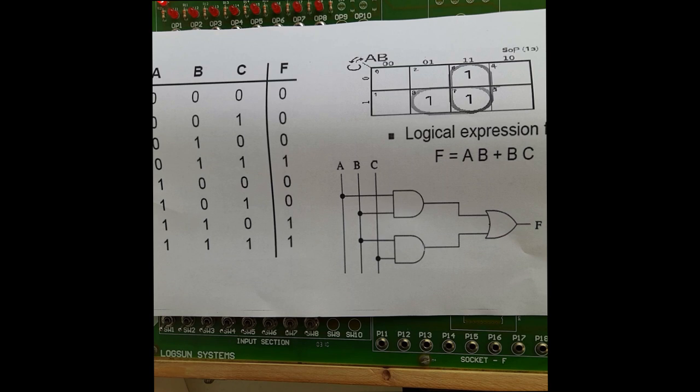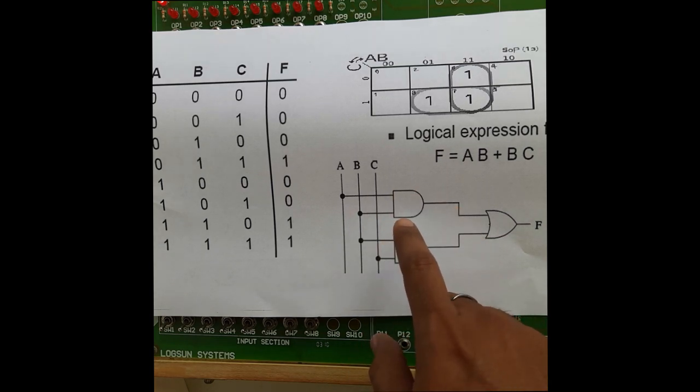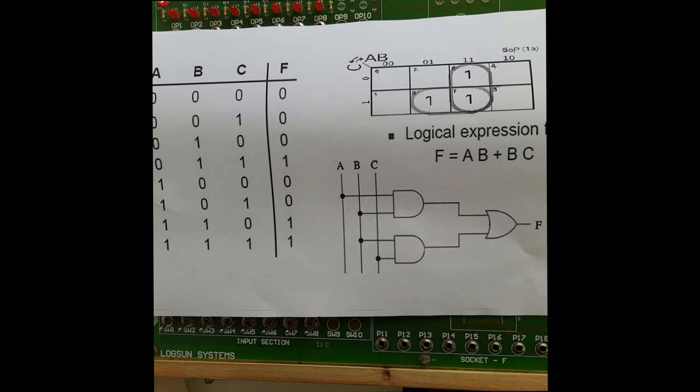It may happen that in your circuit diagram there could be 5 AND gates and 2 OR gates. For implementing the 5 AND gates we require 2 IC 7408, because on a single IC we can implement only 4 gates or only 4 connections. So for the fifth one we require another IC. From that IC 3 gates are unused and only one gate will be used, that is okay, but you require 2 ICs for 5 AND gate implementations.